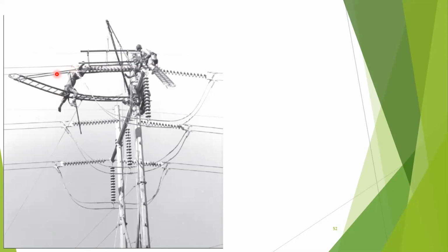This is an insulated ladder, and all these parts are insulated. The strain poles and yokes are put to the conductor and stressed, and when the insulated string is a little slacked, they can remove it and put a new one over here.